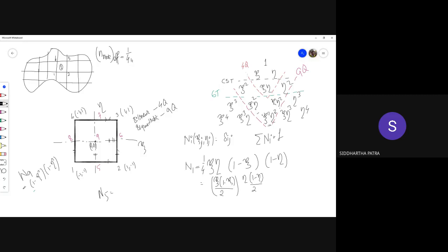Okay. And if you do the same for all the other nodes, what I'm trying to get here is the ratio of number of nodes to number of elements. And that number becomes 1. And actually if you construct a huge mesh, 2D or 3D, with linear or bilinear quad element or trilinear brick element, you'd get the node number very, very close to the element number.